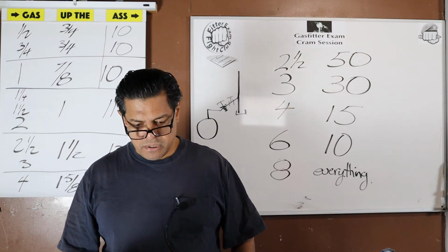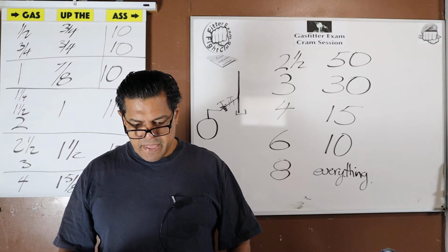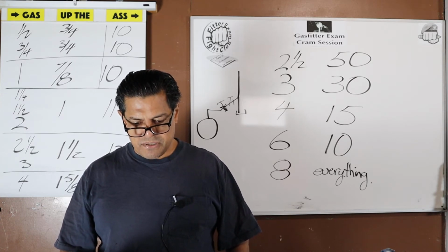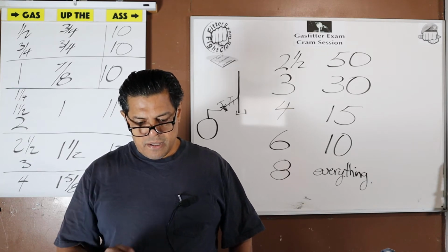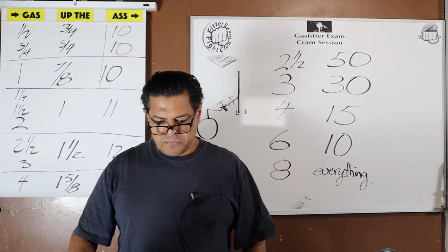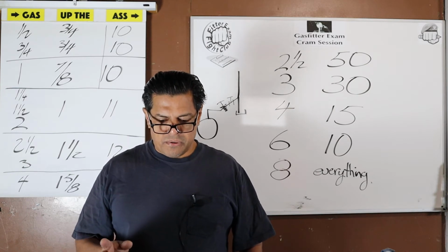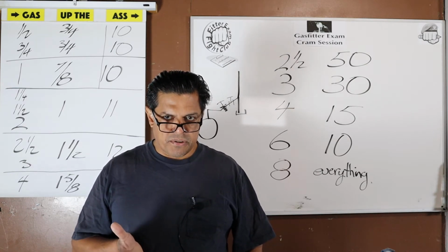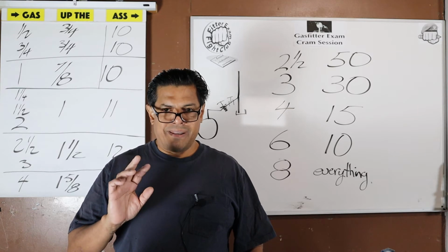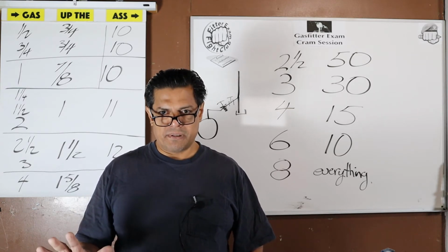Okay. Page 41. Question 10. Gas piping must not be installed in or through B. A clothes chute. A clothes chute. Okay? Now, when we go into the code, there's only so much you can put in these questions. There are a lot of places you cannot run gas piping.